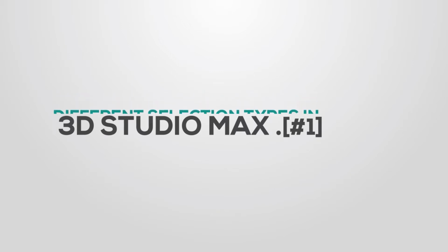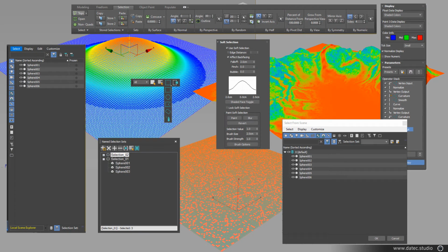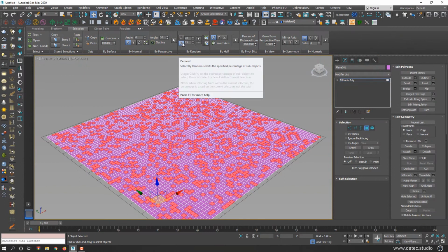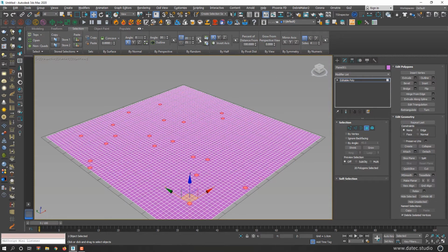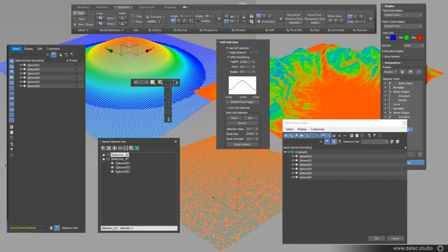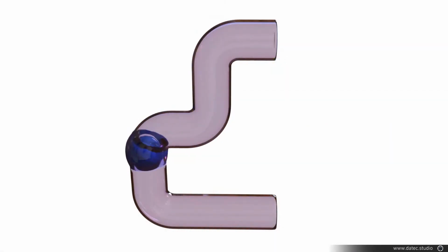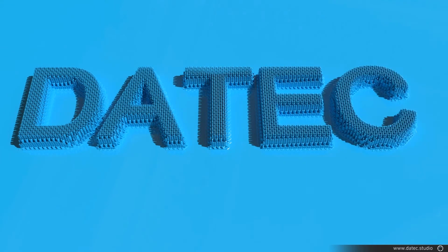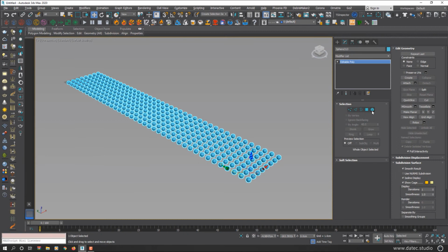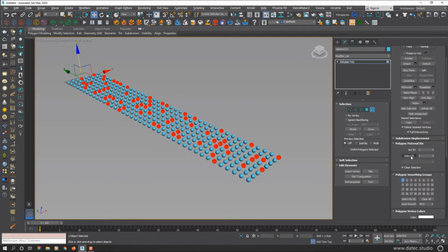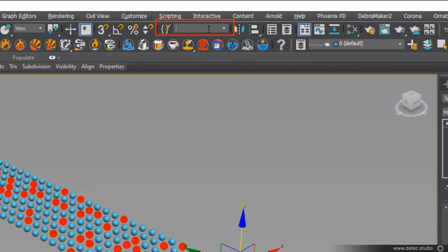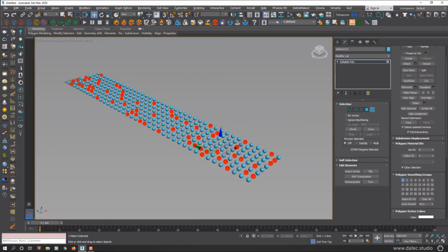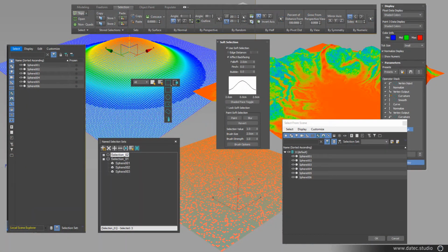In this series of tutorials, I want to introduce selections in 3D Studio Max. There are many types of selection in 3ds Max, such as select based on object, by name, color, similarity, instantiation, layers, hierarchy, and more. Also, selection based on subobject like in editable poly by vertices, edges, polygons, edge count, loop and ring, random selection by ID or so. Other selections like selection set by material, by type, filter selection, and many other features are available in 3D Studio Max.